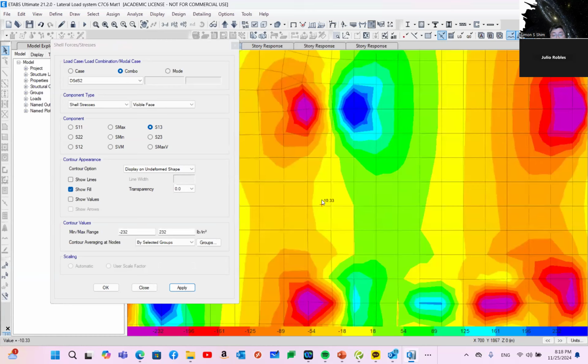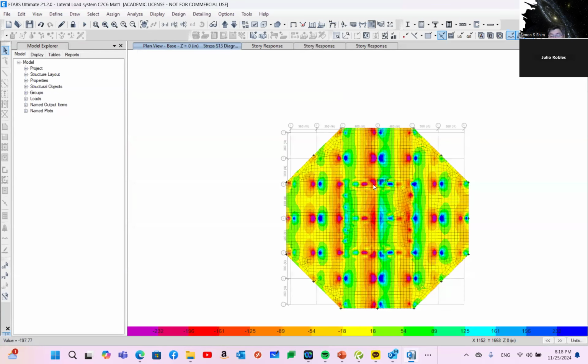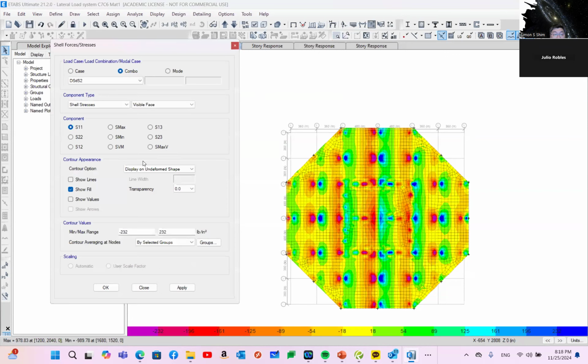Yeah, local, but here much smaller, right? So I think we can maybe roughly average it, so weight it. Otherwise, if you're using this shear stress, this is shear stress concentration, you end up maybe increasing the mat thickness, but I think this is the localized shear stress. So I think your 9 feet is way enough.